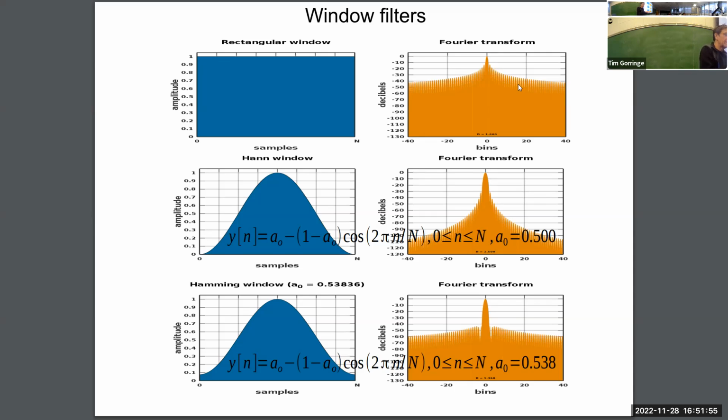At 10, you completely cancel out the input signal. At 11, you completely cancel out the input signal. But in between 10 and 11 complete oscillations, there's a small fraction of an oscillation that's not canceled out, and that gets through your averaging procedure.